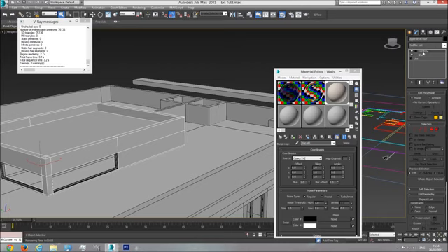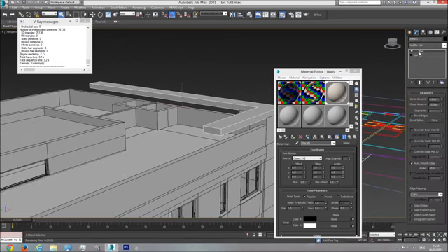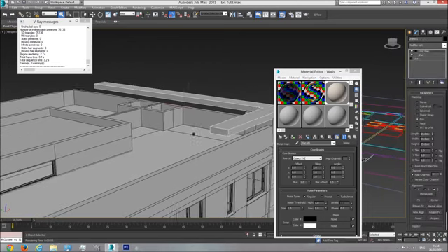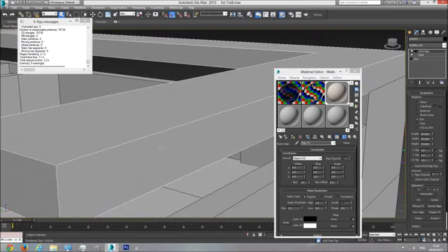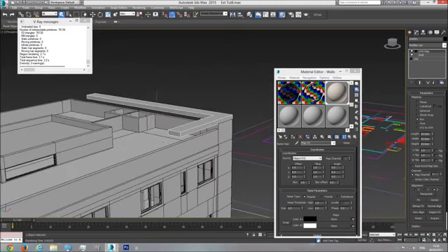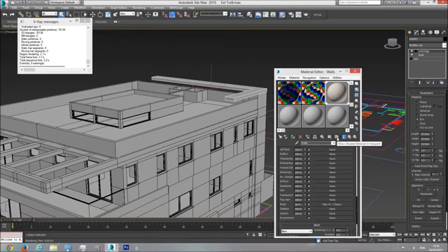So right click on the top modifier in the stack and paste. Also paste it here, right click paste, and now we have the alignment of the UVW map of the texture on the object correctly. Alright, let's go back to the beige color in the viewport. So I'm going to go back to the walls and show shaded material in viewport.